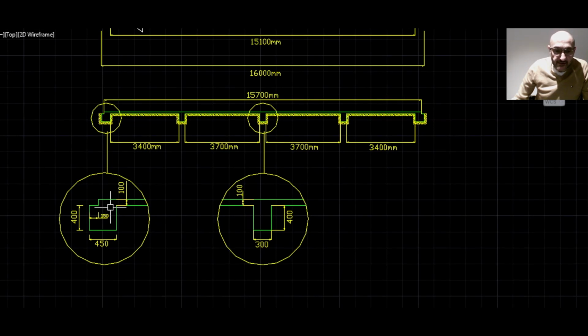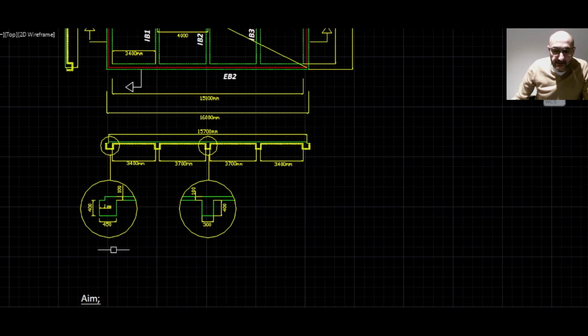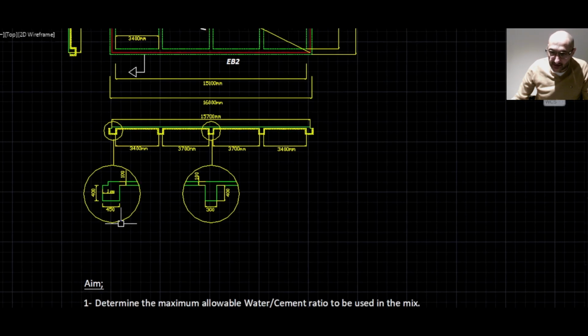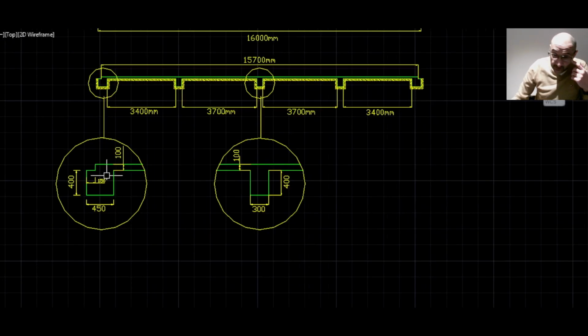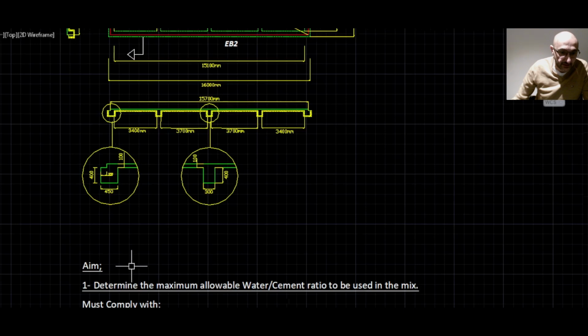The other thing is that a stiffened raft slab is generally slightly tapered. If you look it up in some textbooks and the Australian footing code AS 2870, you'll find that it's slightly tapered. However, in this case, we will just assume it to be a straight edge beam, for simplicity when we calculate the volume towards the end of the presentation.